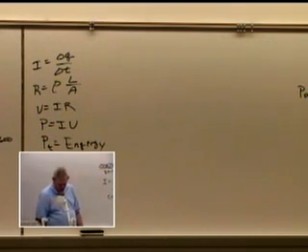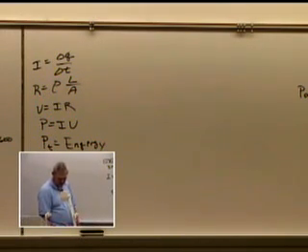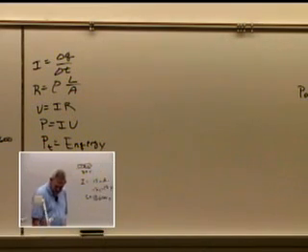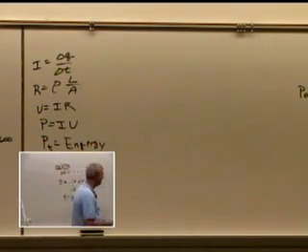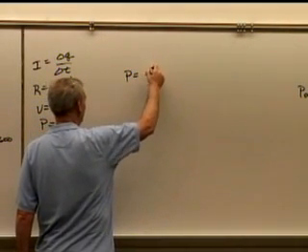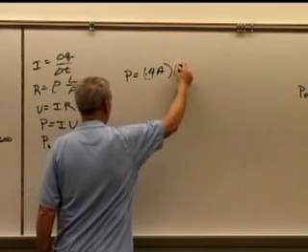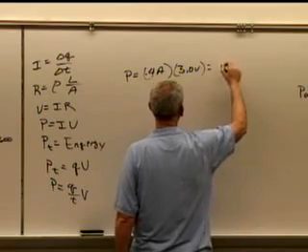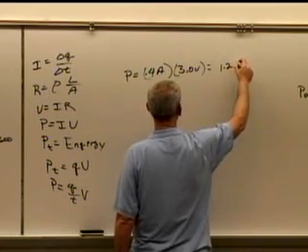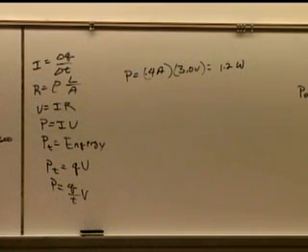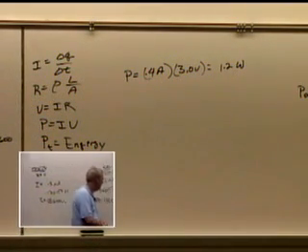All right. So with that in mind, let's go through this. The voltage is 3. Find the power. Well, if we know voltage and amperage, power is pretty easy. P equals 0.4 amps times 3 volts. That should be 1.2 watts. And the energy that it used?